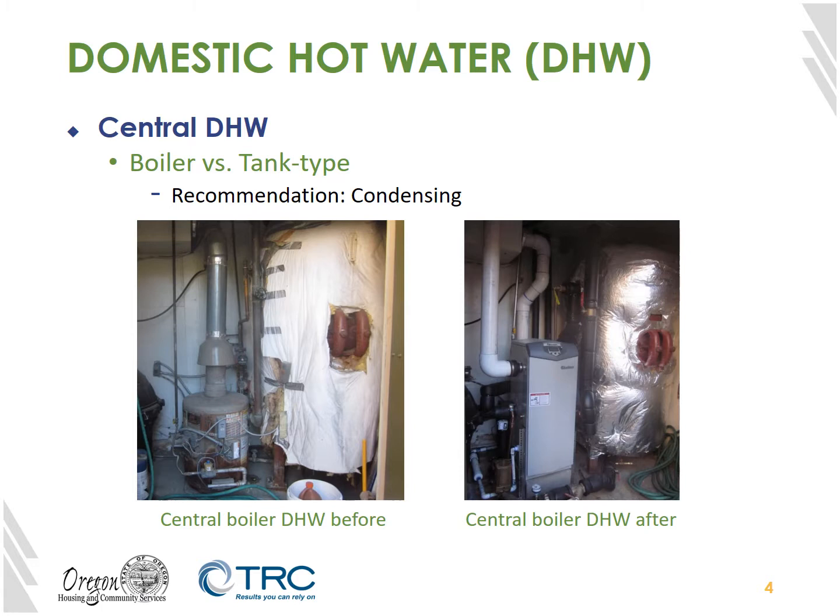Particularly in more moderate climates, hot water is a very substantial energy use in multifamily buildings. Central water heaters are uncommon in this region and are typically gas-fired systems. In buildings that do have these systems, however, the tank may be a part of the water heater or separate from the boiler. In either situation, a condensing water heater is a very efficient option and can bring the efficiency of the system from approximately 80% to over 95%.